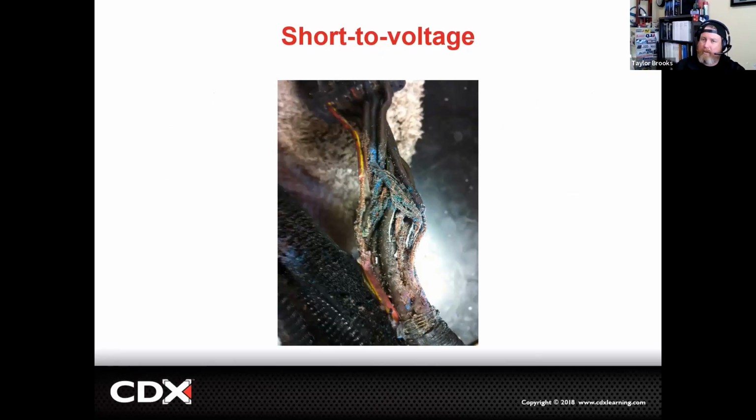Quite often manufacturers will put flooded lead acid batteries in the engine bay so that they're easily accessible. They'll be kind of high, and usually below the battery tray they can have control modules. Well, what can happen is if the battery outgasses or it can leak electrolyte out, that will eat away the insulation, and then all the copper can touch each other, and you can get a short to voltage very similar to what I have photoed here.